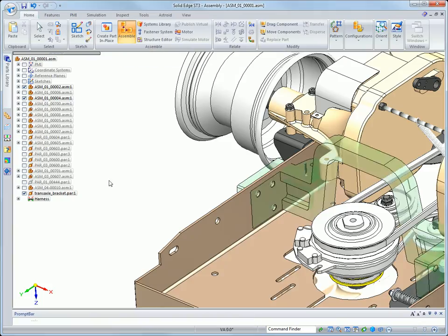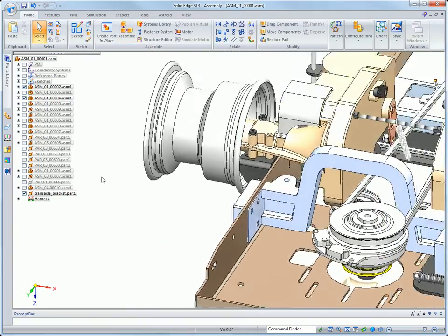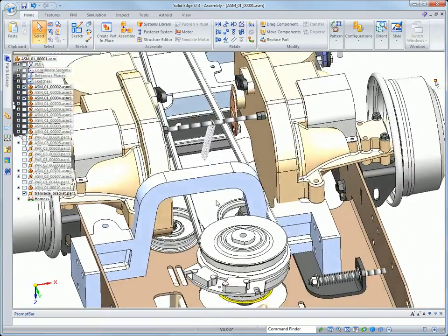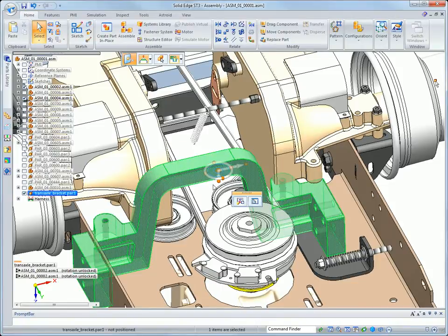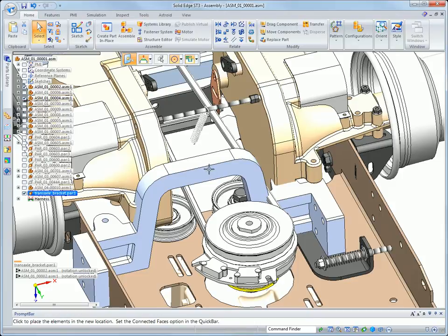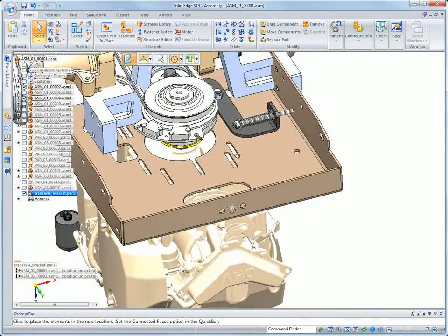Now that we have that in position, the only thing left to do then is to center this within the sheet metal part. And we're going to do that using synchronous technology. We can select the entire model and position the steering wheel to the midpoint and align it to a key point within the assembly.